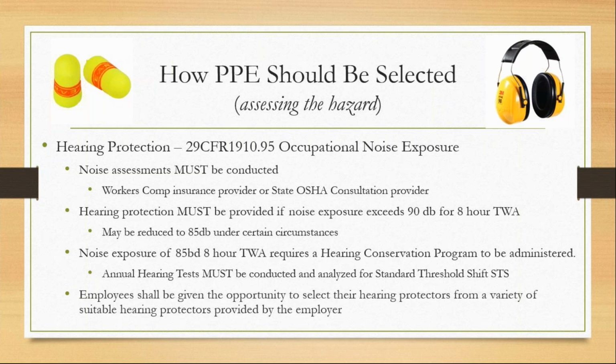So if you have to get the noise inside that person's ear down to 90, then those will protect up to 118 decibels of noise to get it down to 90. It's really not enough, and that's only if they wear it correctly. So you may have to put them in earplugs and muffs.